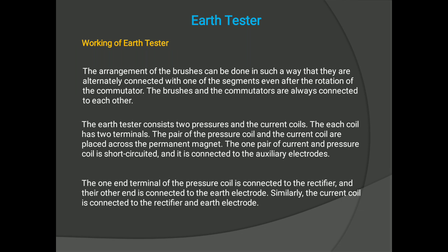The alternating current in the soil will produce an alternating drop in the soil, but the potential applied across the moving coil must be direct because the ohm meter, a moving coil instrument, works on DC alone. So, for changing the alternating drop into a direct drop, a synchronous rotary rectifier is also attached, which is shown in the figure.